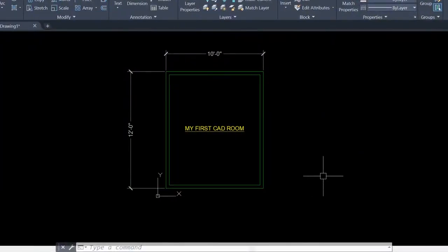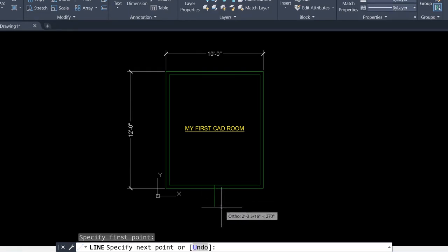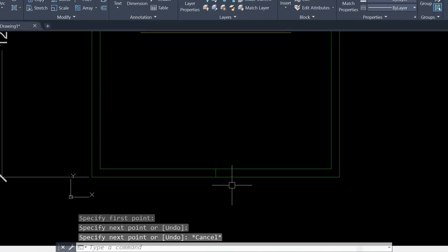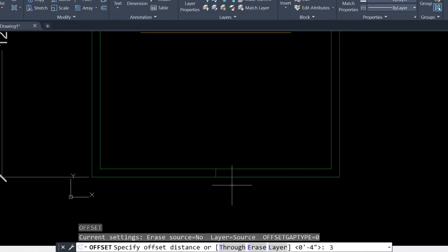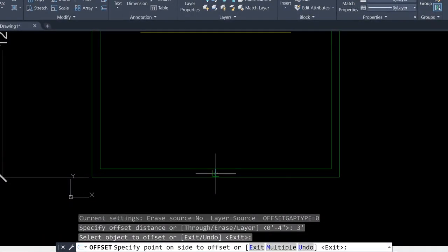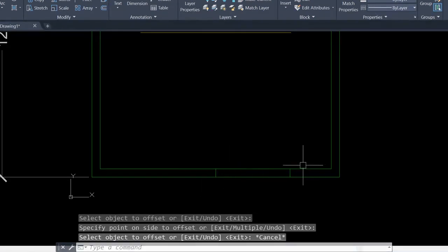Okay, now let's add a door to our room. To do that, I'm going to use the line tool. I'm going to go ahead and click over here to line. I'm in the wall layer, and I'm going to snap to the midpoint of this wall and drag my mouse this way. And I'm actually going to zoom in, drag it to the midpoint of that other, so it's a 90-degree line. Just hit escape. And I'm going to hit O for offset. And I'm going to offset 3 feet. So 3 apostrophe enter. And that gives me a 3-foot offset. So I'm going to click once here, drag my mouse in the direction I want that offset, left click once, and there I've offset a line at 3 feet.